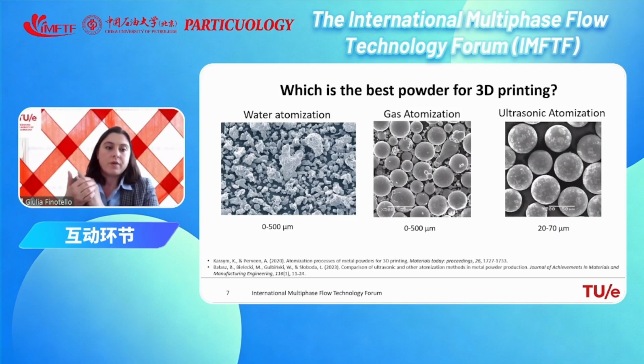For gas atomization, after the impinging and the cooling, the surface tension is able to reform a spherical particle much quicker, while for the water atomization, when you are still in the breaking of the streamer, breaking of the droplets, the cooling is fast, and then these non-spherical droplets are retained because you are cooling them down while they are still stripping, and they are still deforming.